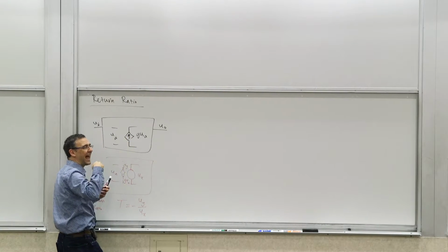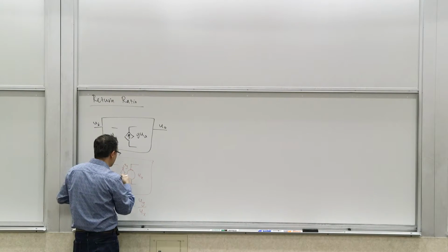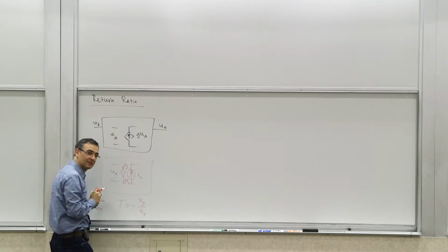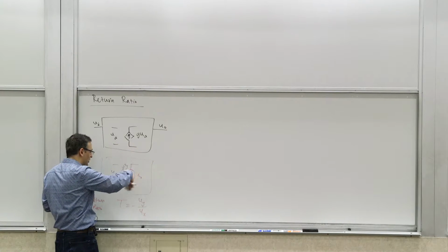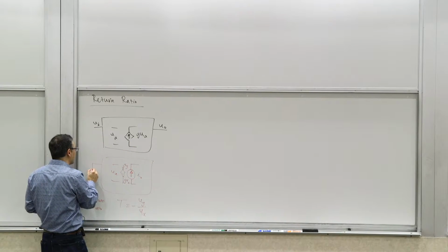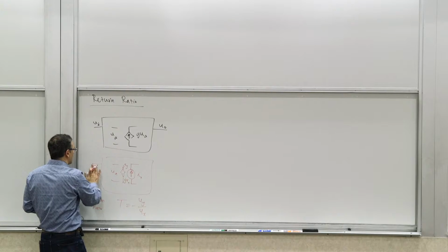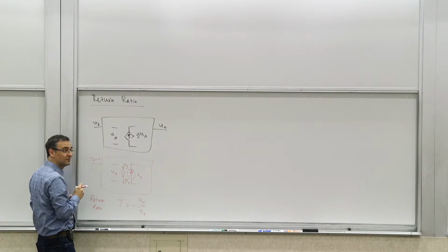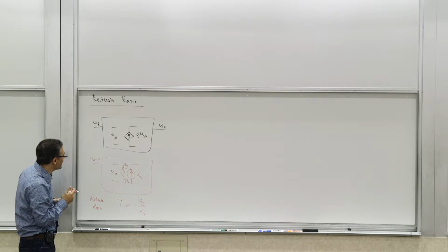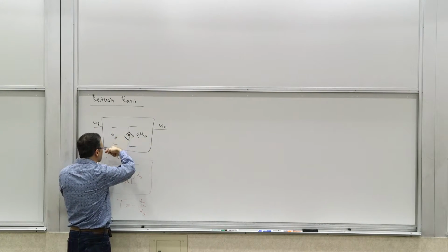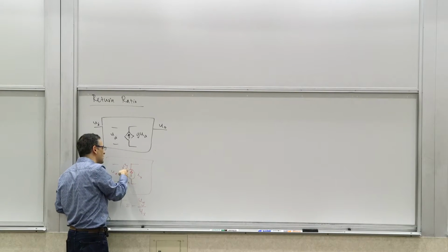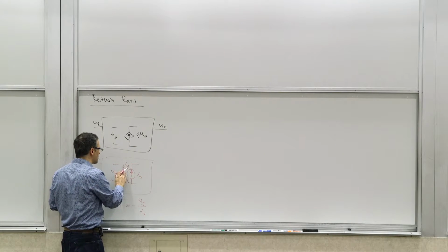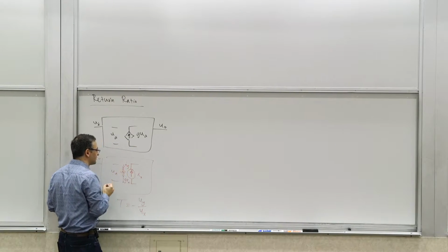take this current source out, replace it with an independent current source of value Ix, and let the circuit do its thing. And it basically, by the way, nulls the independent source. So Ui is 0, and the input is 0. The independent sources are 0. And see what fraction of this thing comes back to produce an Iy if that dependent current source was sitting here.